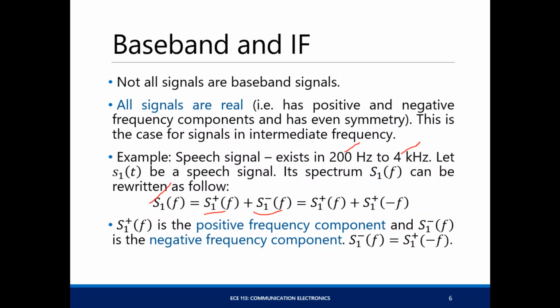And we have right here, since this signal exhibits Hermitian symmetry, it follows that this S1 negative, the negative frequency component, is your positive frequency component reflected.